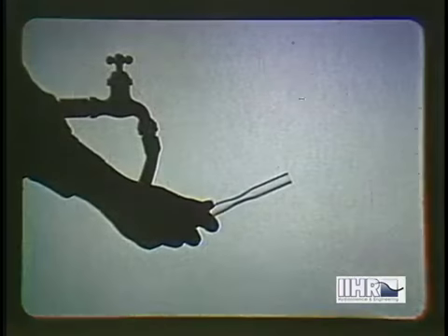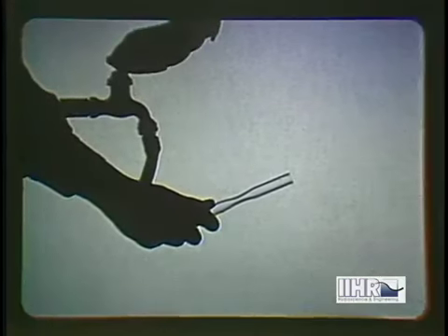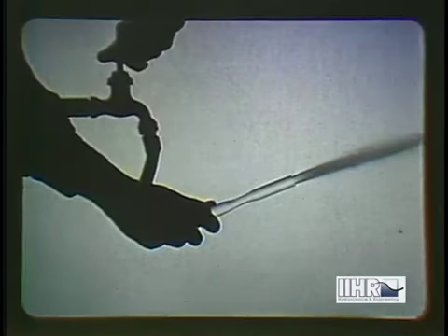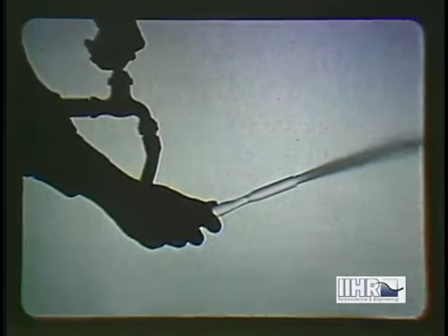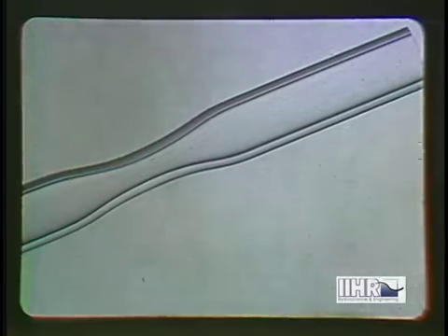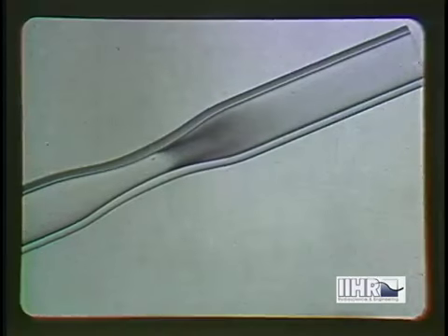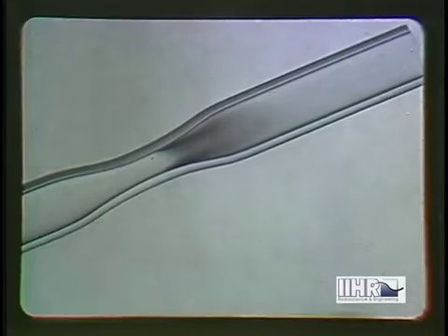Another phenomenon that limits use of the pressure-velocity relationship is called cavitation. As Osborne Reynolds demonstrated with a glass Venturi tube nearly a century ago, the velocity can be increased to the point that the pressure drops locally to the vapor magnitude. The liquid then begins to boil at normal temperature.